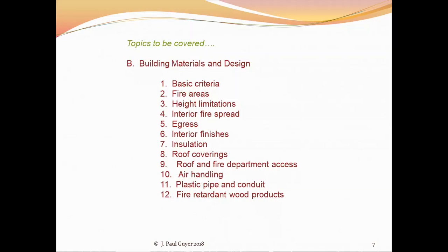You've got a fan blowing air all over the building, and it has been recognized in recent decades that the air handling system is a significant concern in the event a fire breaks out in the building, because it breaks out, say, in one location and there's a lot of smoke being developed and the air conditioning system is sucking this smoke out of the place where the fire started and blowing it all over the building and creating a hazard for people in other parts of the building other than where the fire actually broke out.